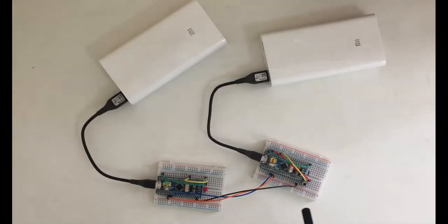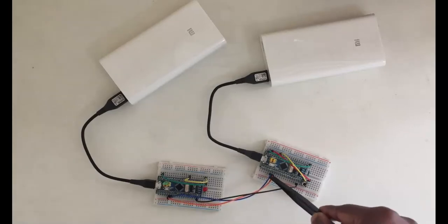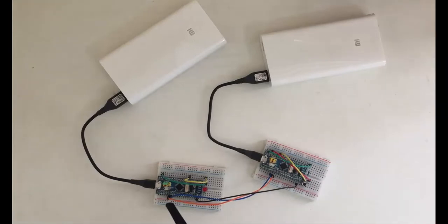So how it works is, we have RX and TX of this one connected to TX and RX of this one, and the ground is connected, and through it transmits the data through UART transmission. To show it really works through UART, I'm going to remove these three wires. I'm going to connect a LoRa module to these three wires and another LoRa module to these three on the other side. So I'm going to show you how it works.